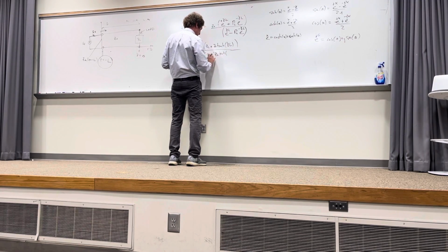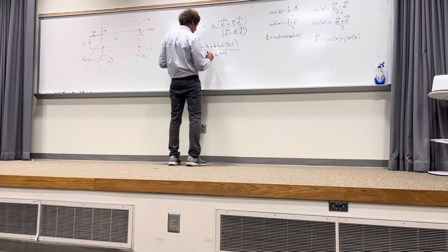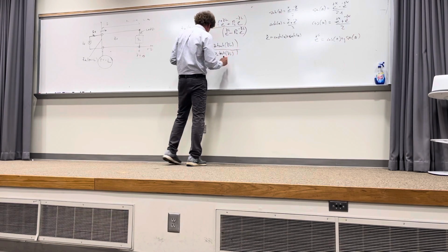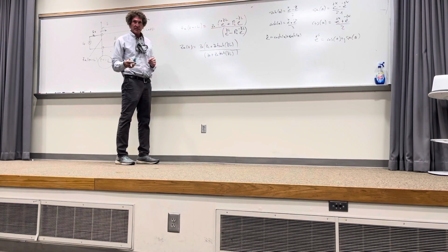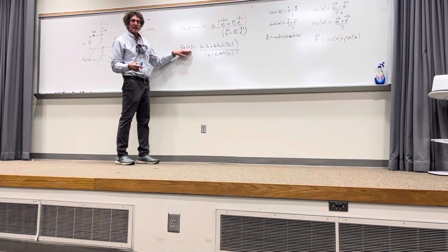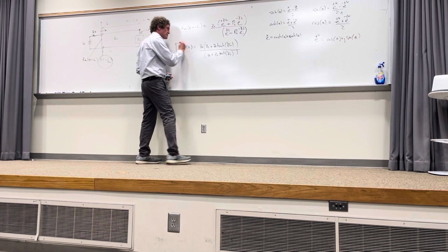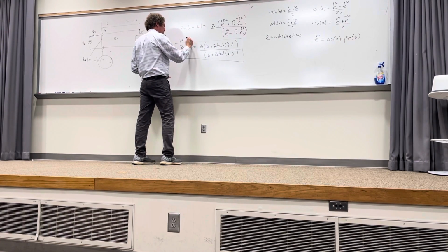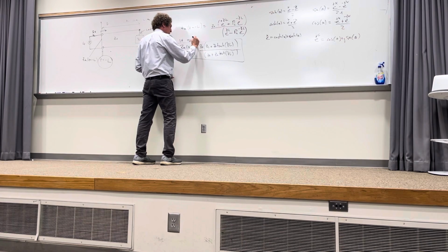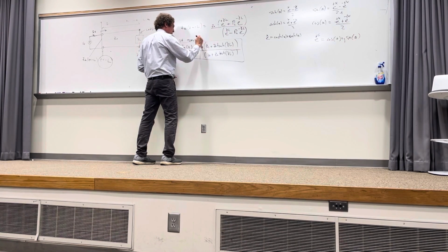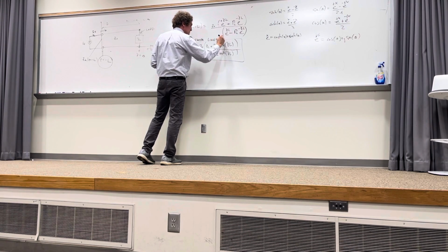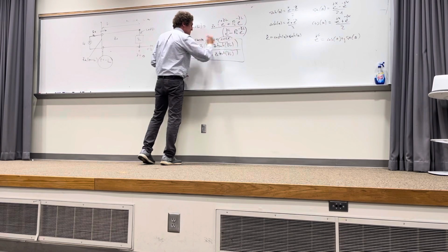Minus part. No, I'm sorry, plus the hyperbolic tangent of gamma L. Now, I gotta tell you this. You use this equation only if the transmission line is lossy. So only if it's lossy.